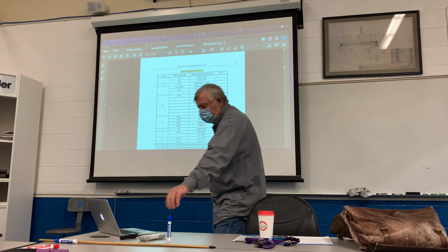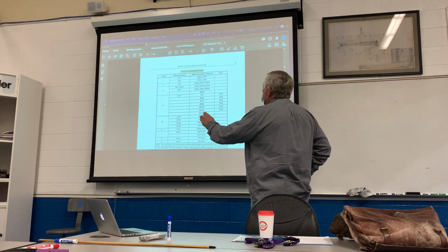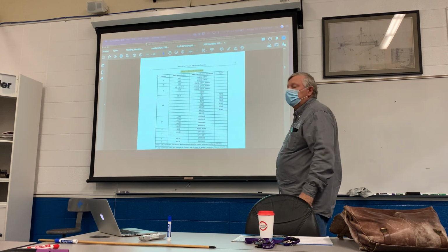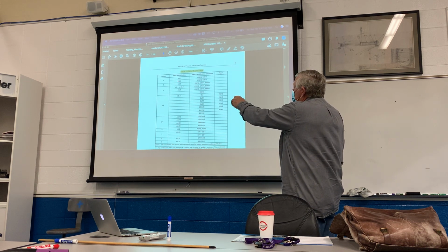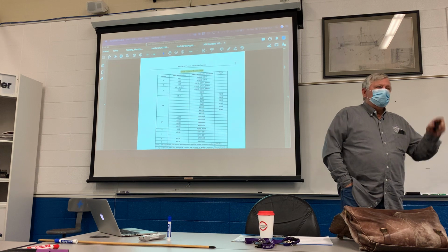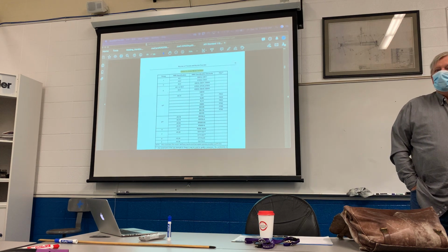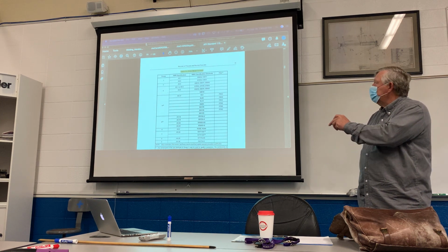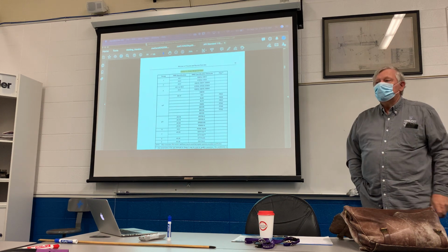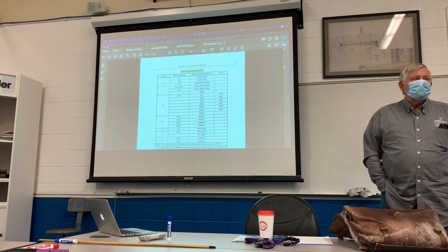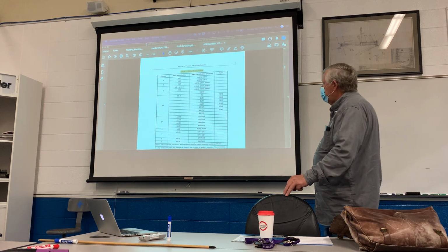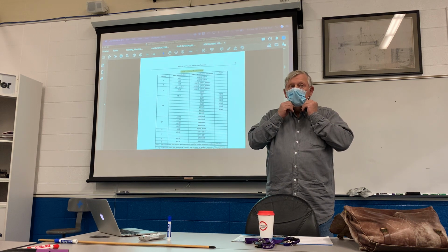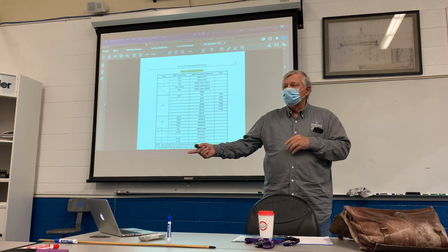Like we talked about a little bit, if the procedure calls out a rod from group 1, and it says specifically A5.5, and the procedure was welded with 70-10, can there be a different rod used? You use 70-11. There's one other rod that you can use. You see what I'm saying? Okay. You will find sometimes on procedures down in the comments section or somewhere else on that, or even on the PQR, you have to look at the PQR sometimes.